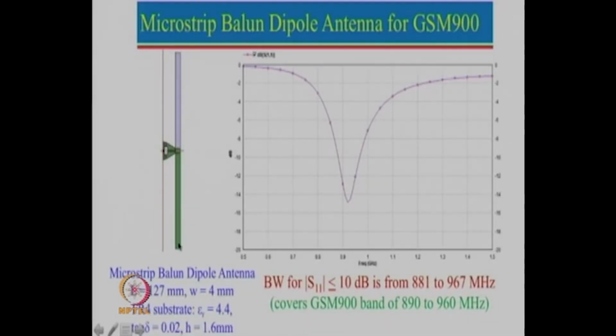Here, this is a dipole antenna which is printed on an FR4 substrate. It is a lossy substrate and a very low cost substrate. On the upper side of the substrate, this half of the dipole is fabricated, which is lambda by 2 in total length, so approximately lambda by 4 each, and on the other side of the substrate the other half of the dipole is connected, and on the bottom side you can see that there is a triangular thing which acts as a ground plane for the top feed which is coming like this. So, basically this is the point where we connect a coaxial connector.